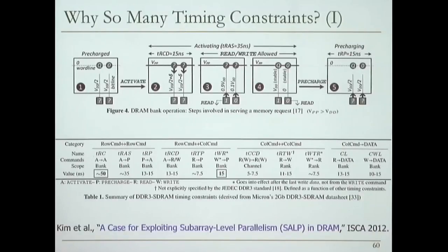Well, you could also say, and people have said this, I don't want to do it this way. This is very synchronous, and as a result I need to keep track of every single thing. Why don't I make DRAM asynchronous? Whenever I send a command, and whenever the DRAM is ready, it knows when it's ready, it sends an acknowledgement to me saying, I'm done with this command. That's an asynchronous mode of operation. That could potentially achieve the benefits of this.